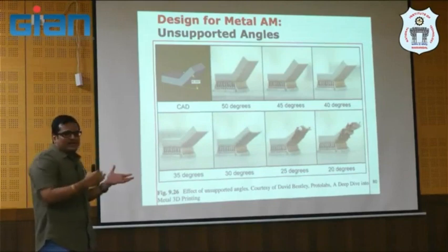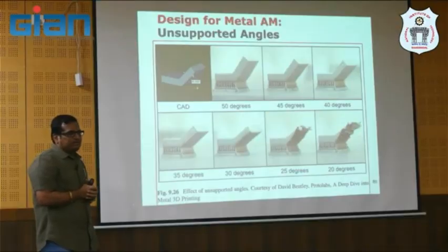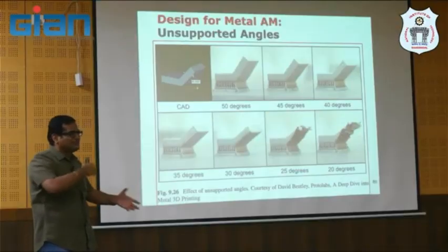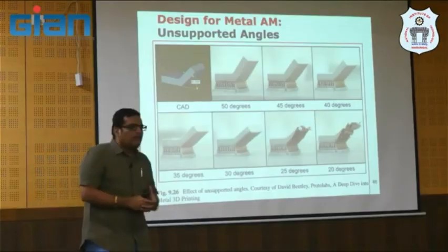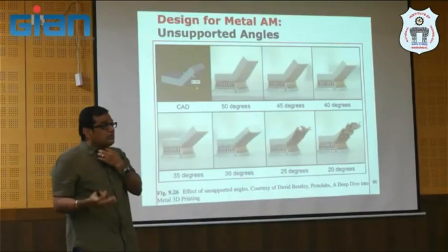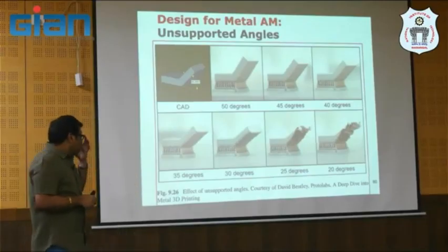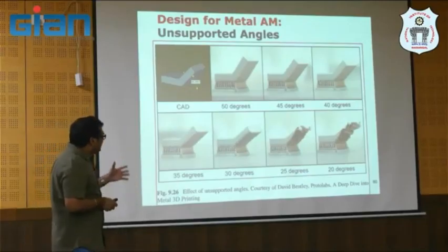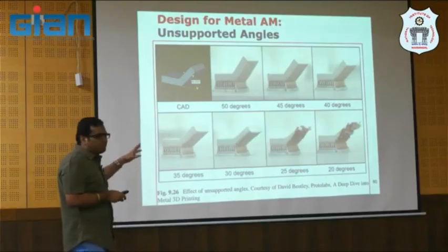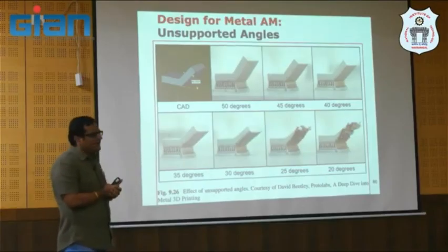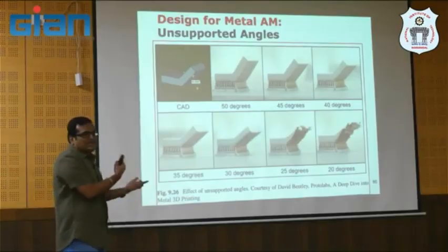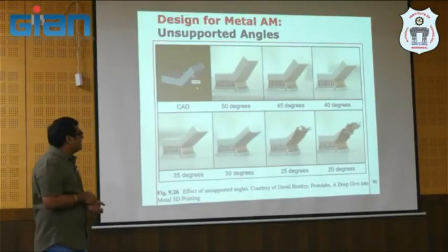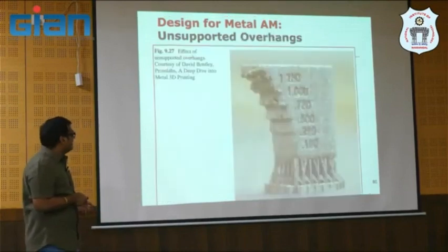And then your conduction, right? It's going to play a role. Anyway, we have an expert here with whom we are going to discuss all those aspects, conduction, all that thermomechanical modeling of it. So anyway, your unsupported angle is going to play a major role. If you are not following that thumb rule or those guidelines with supports, then you are trying to build, and ultimately you may not succeed in your build.